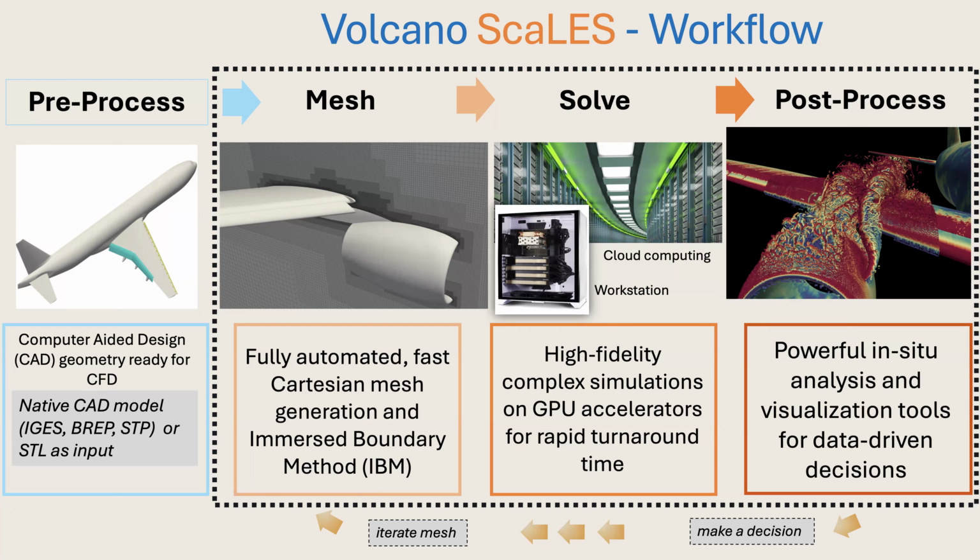And once you have the coarse grid, you don't change the relative resolution between the fine grid section and the coarse grid section in that optimized coarse grid, and you change one line of input parameter, that is minimum delta x. So you can start doing grid resolution studies by changing minimum delta x.